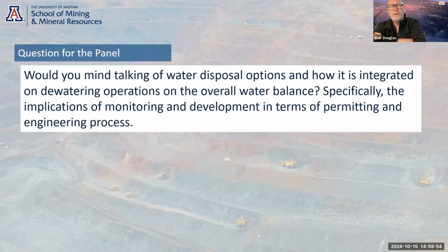Then you're in a reactive position. You're no longer proactive, so having that flexibility is good, but it comes at a cost. There's an economic trade-off in how much flexibility we want in our surplus water account for the variability we have, not only in hydrogeology uncertainty but in mine planning uncertainty, because mine plans can change. If there's higher grade ore and an opportunity to sell at the market, they'll want to pump more, and pumping more means they need to dispose more.